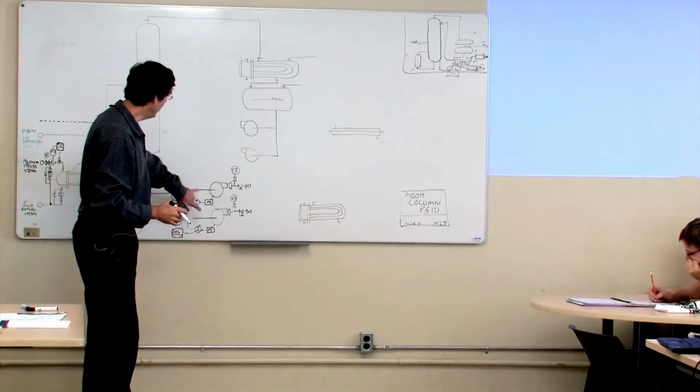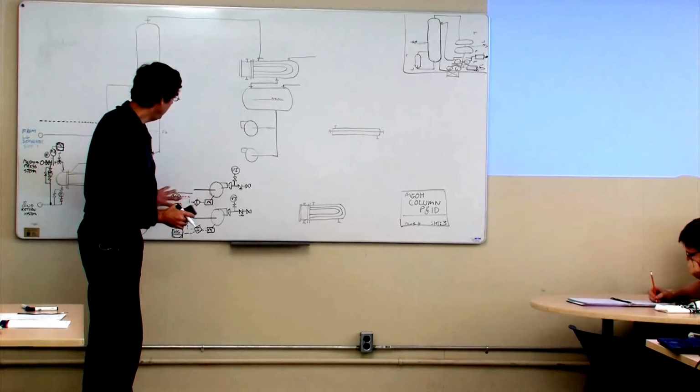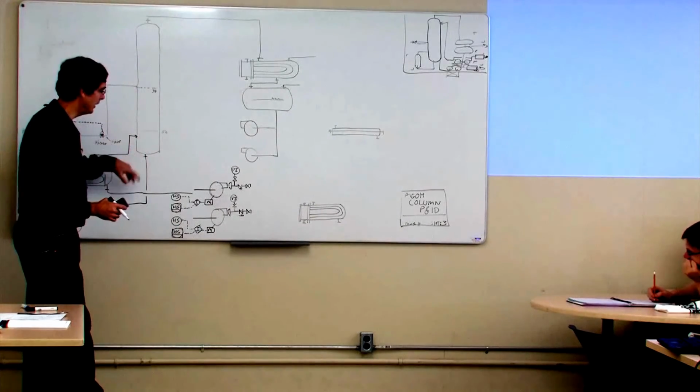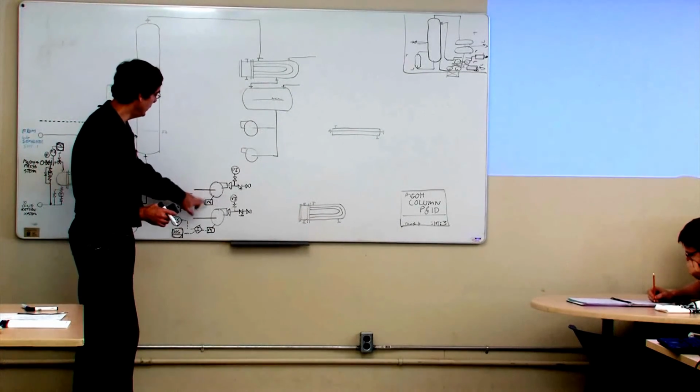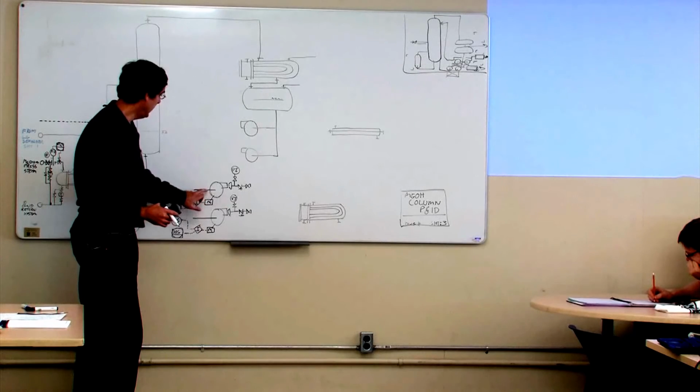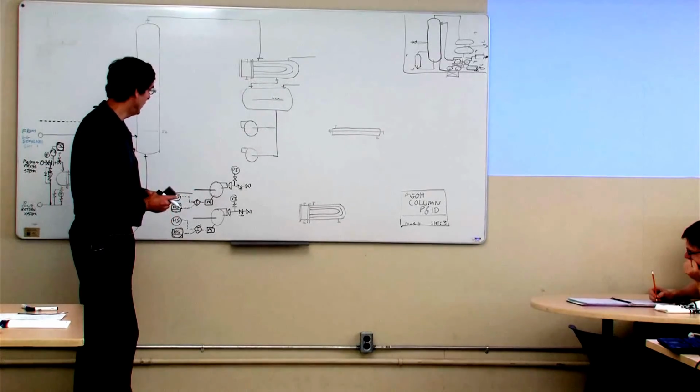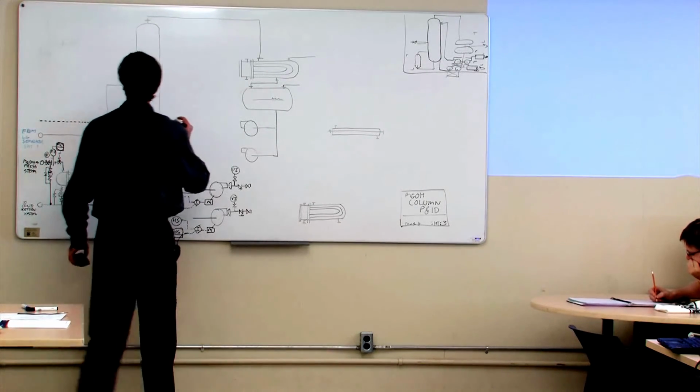If you're worried about there being solids flow in here, maybe even for startup or anything like that, then it's not a bad idea to put strainers in the pump sections. I don't think that's shown on the slides that I gave you guys yesterday, but there's a couple of different strainers. I'll just write this down.